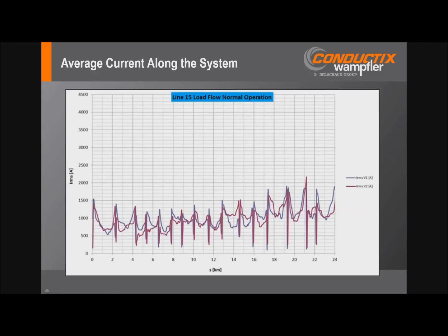That's a good question. Pickup guides. Yeah, anytime you're making a transition there, it can be a bit difficult. Well, I can tell you that for smaller V-contact surface conductors, we have managed collectors through switches. Now, these are switches where you've got 20, 30 millimeters maximum of gap up to 100 kilometers per hour. But a pickup guide, really where you're disengaging and re-engaging the collector, we've done some third rail systems.